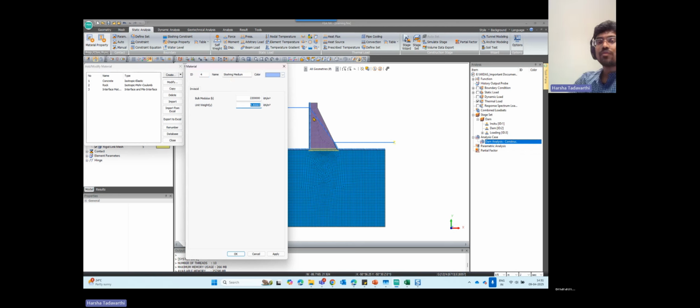And then instead of considering the Westergaard's mass, you can create the sloshing medium, and then the software will apply the forces onto the dam according to all the frequencies of your earthquake motion. The pressure applied onto the dam will be different because you are now defining the sloshing medium rather than Westergaard's equation. Yes, that can be considered in this software by using sloshing medium.